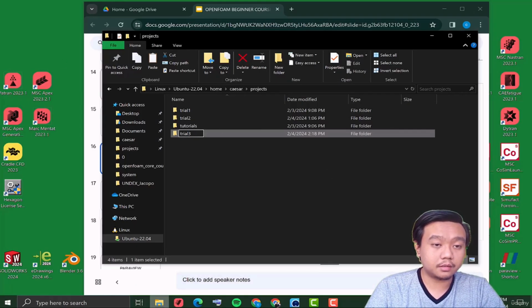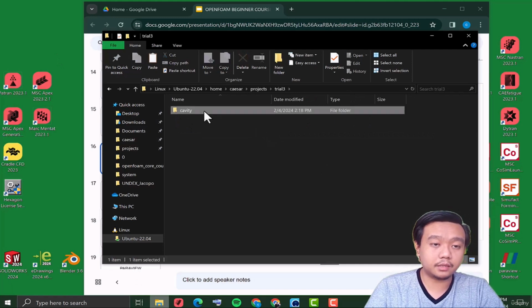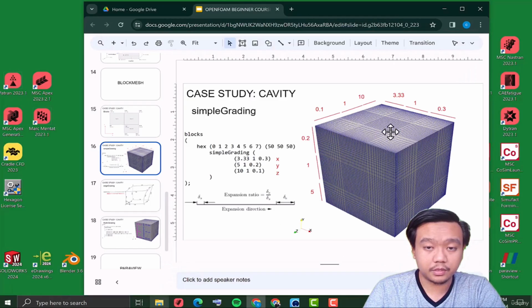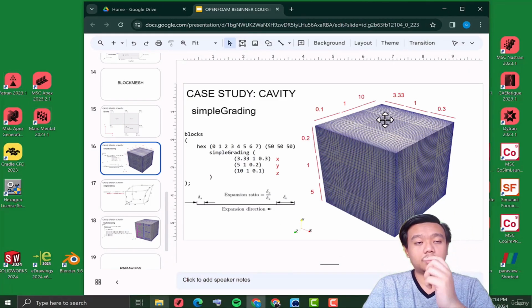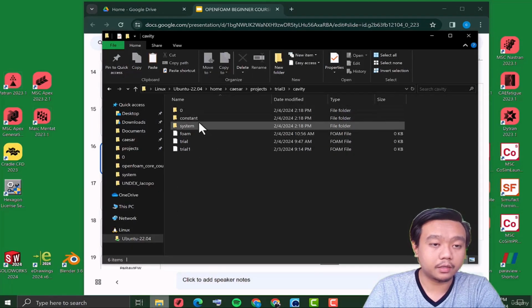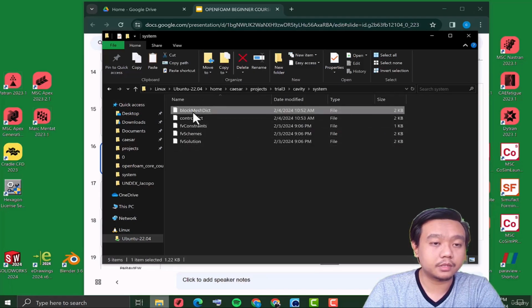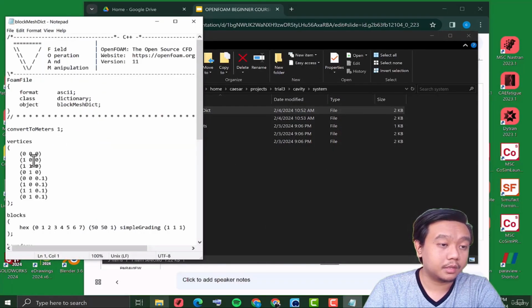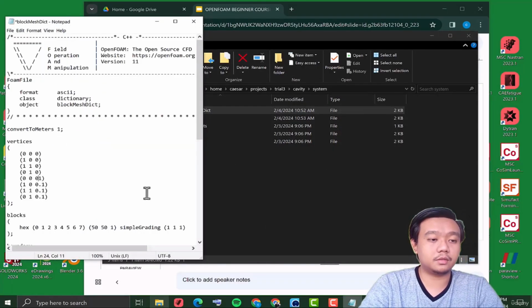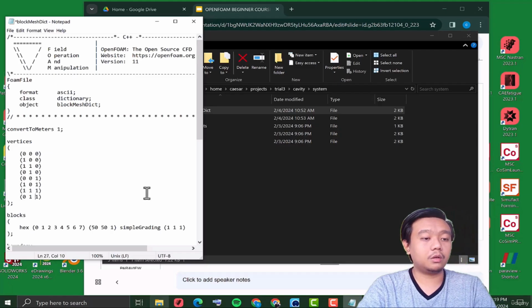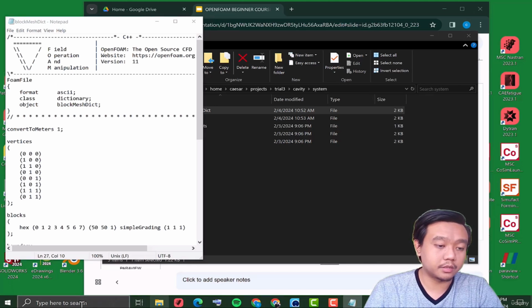But before we edit or run, we make the block the same size in every direction, so it will make our example more obvious. Just take our block mesh, then let's make the z direction also 1 meter, so we have all 1 meter in 3 dimensions.